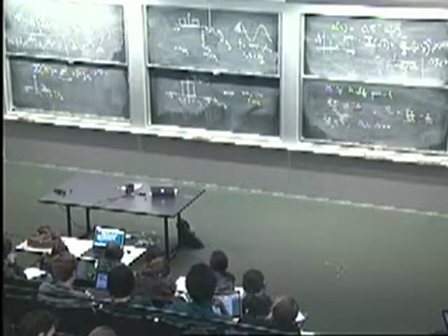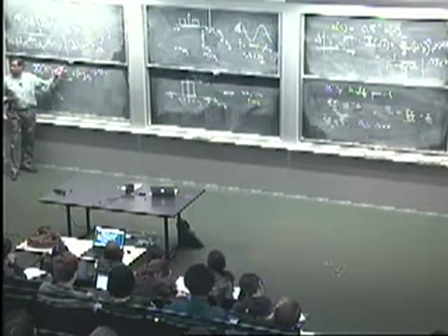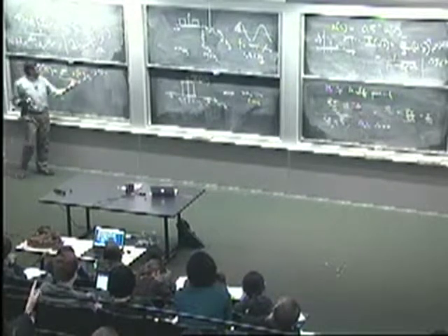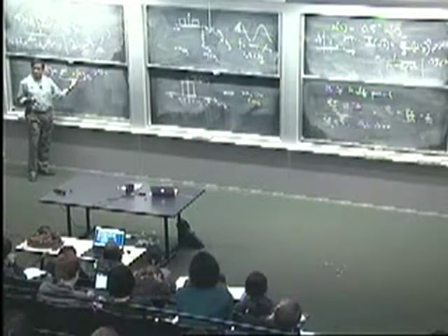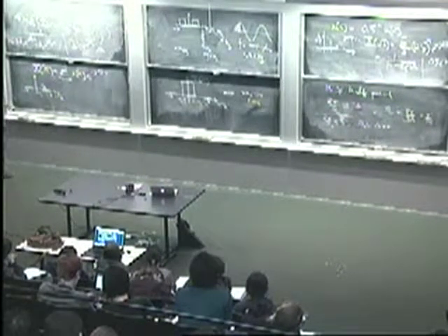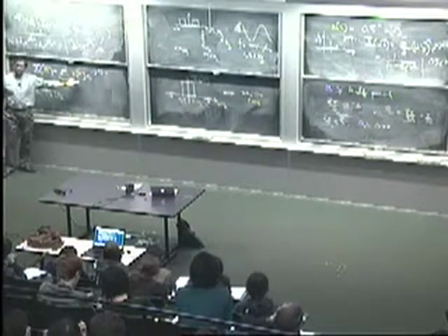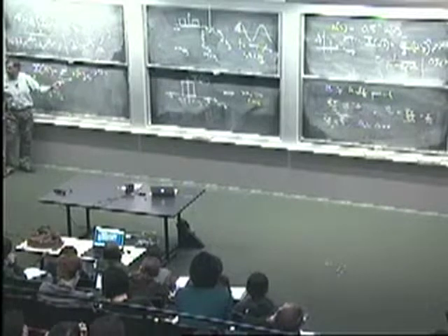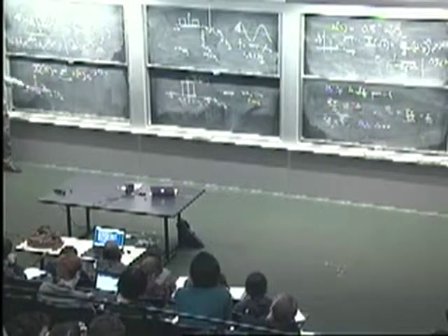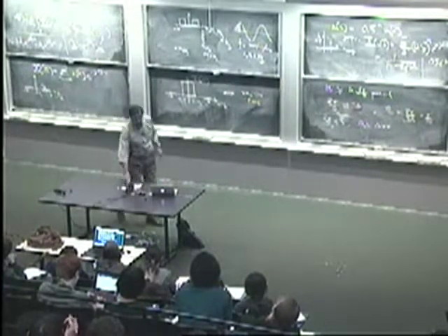Any thoughts here? It's unlikely that my summation is going to go from minus infinity to infinity, because I'd be waiting a long time to collect that signal, right? So in practice, what we're dealing with are signals of finite duration, typically assumed to be zero outside of that interval, though you might have reasons in some contexts for assuming otherwise. We're always going to take finite length signals. So the summation will be over a finite interval. And we're going to want to compute the DTFT on a finite grid of points. And that makes for some simplifications.